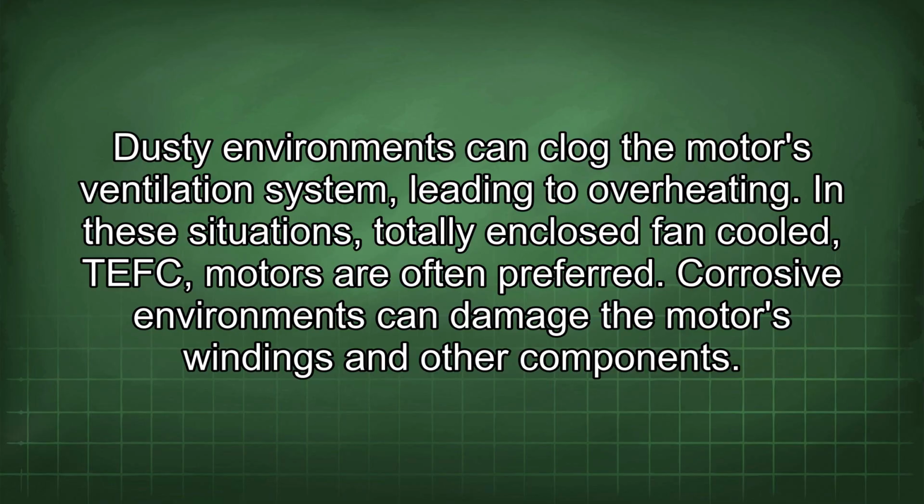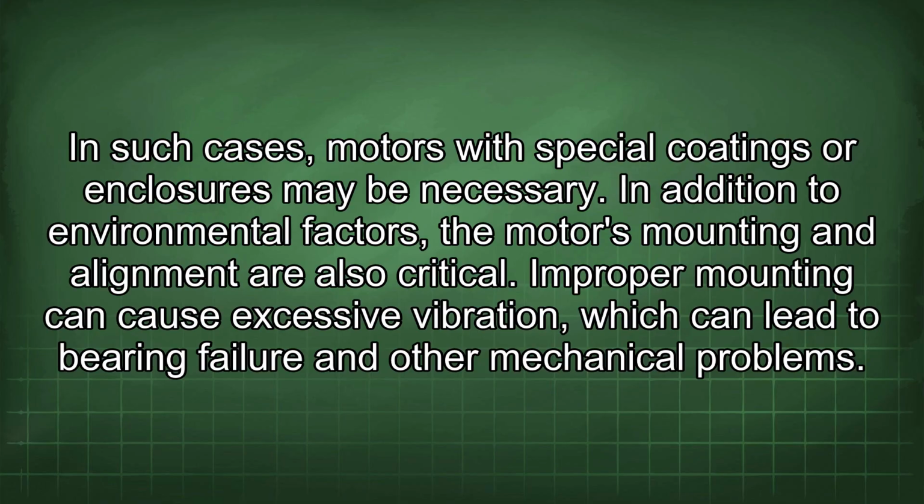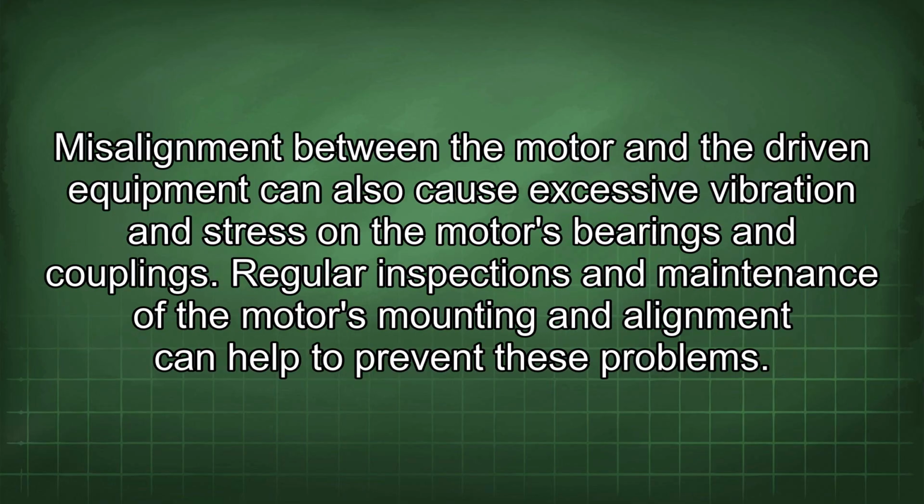In these situations, totally enclosed, fan-cooled TEFC motors are often preferred. Corrosive environments can damage the motor's windings and other components. In such cases, motors with special coatings or enclosures may be necessary. In addition to environmental factors, the motor's mounting and alignment are also critical. Improper mounting can cause excessive vibration, which can lead to bearing failure and other mechanical problems. Misalignment between the motor and the driven equipment can also cause excessive vibration and stress on the motor's bearings and couplings. Regular inspections and maintenance of the motor's mounting and alignment can help to prevent these problems.